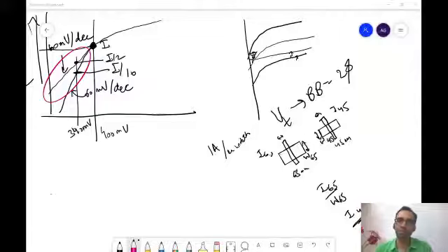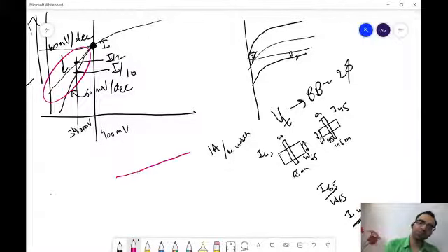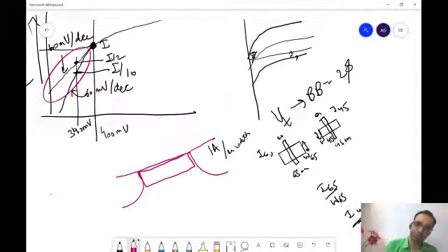Kandeep? Yes, sir. Sir, in the last class, you said that in smaller technologies, the channel is already doped so much that you cannot increase the doping further. Why is that? Again, to manage the short channel effects. Let us look at it like this. We talked about the rectangular assumption, that in long channel devices, the channel region over here is rectangular in nature.